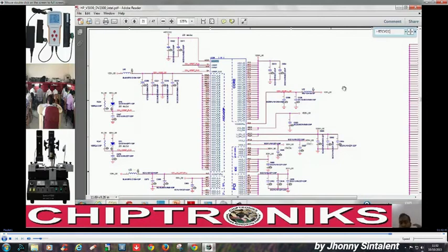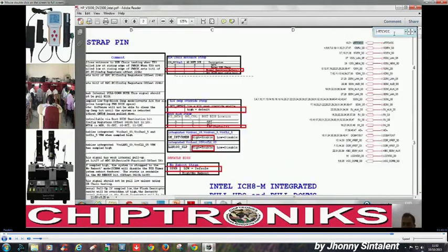Kindly note, whatever your diagnostic way may be, whatever you are currently doing, just go through my steps and you will find that you will miss nothing in between while testing this way. So now we have checked. Now we are going to measure VCC RTC. VCC RTC is connected to +RTC_VCC, so we search from here.